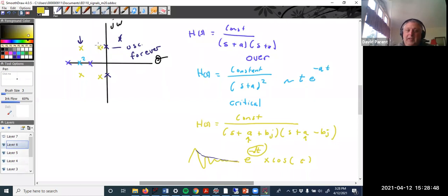And be careful, because some people will call things with too many oscillations unstable, right? Even though the real part will be on the left-hand side, these oscillations are too high and too long to meet your specification. But in this class, I will just go by the strict mathematical definitions, right? But as a control systems engineer, people might use the term unstable when they really mean an underdamped system with a small value of zeta.